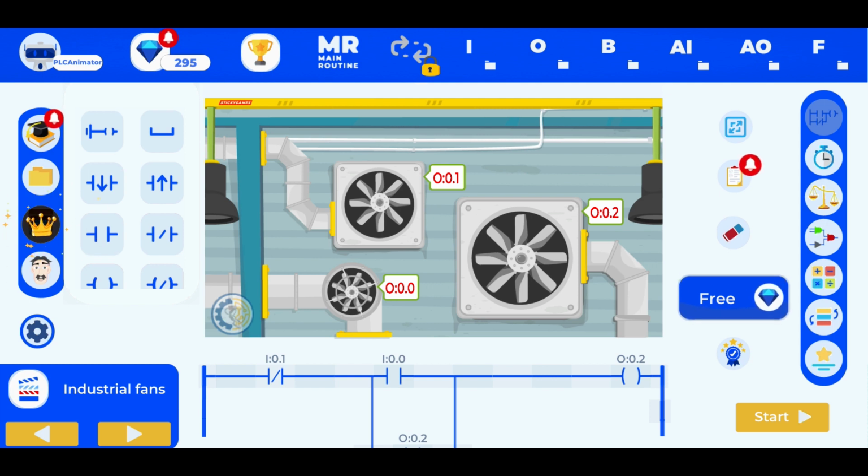When they're normally closed, in this case, for example, our red button for stop, we are going to connect physically as normally closed on one end of my block, and I'm going to connect it to my PLC input.